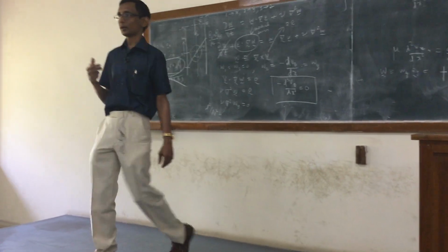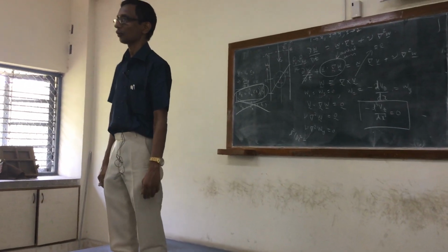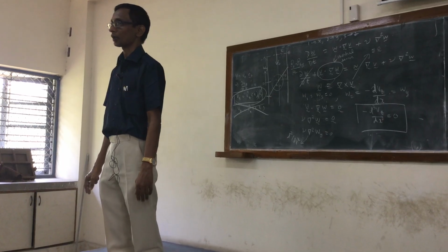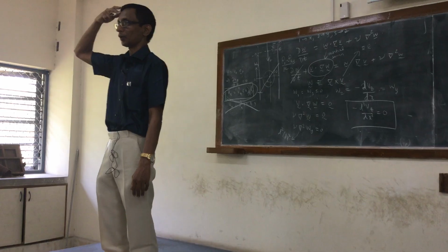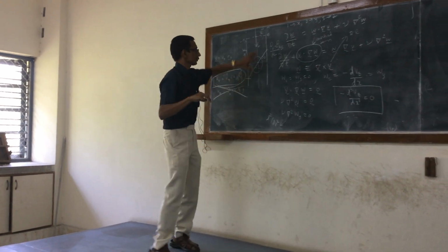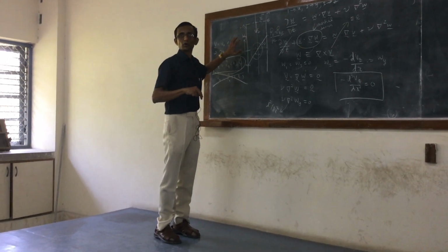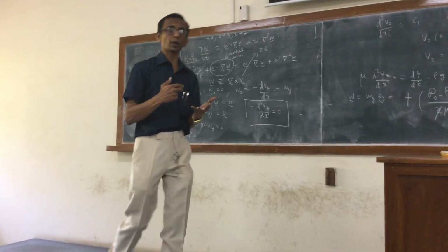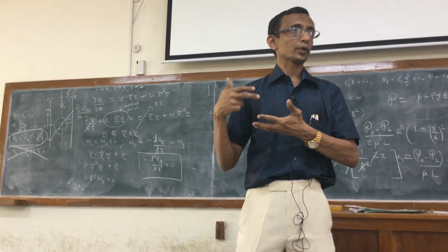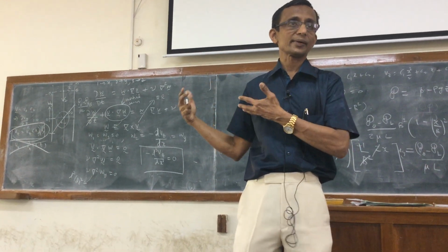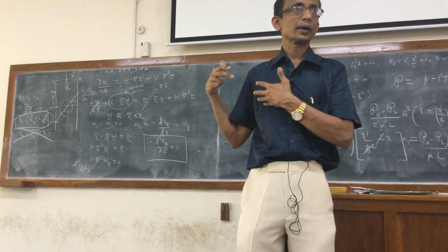Probably make an assumption of an irrotational flow, certainly not near the solid wall. And this is the basis of the boundary layer theory. So the boundary layer theory doesn't describe the vorticity flow, but it divides the flow region into two parts. One, a small layer; the smallness of the layer will depend on the Reynolds number and so on, which will be discussed shortly in the next topic, right?